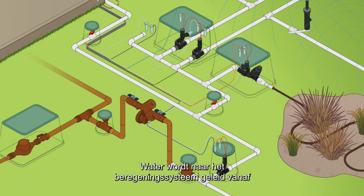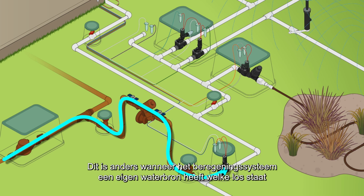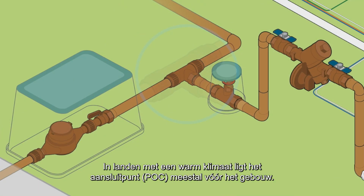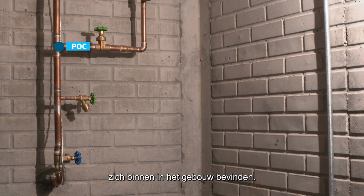Water is directed to the irrigation system from the delivery line that supplies water to the home or commercial building. This will be different if the irrigation system has a dedicated water source separate from the meter to the home. In warm climates, the POC is usually before the building, and in cold climates, the POC could be inside the building.